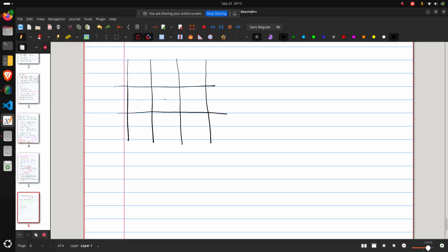Back to our Cartesian well organized meshes. This will make our life simple, but now you know how to go from a structured to an unstructured mesh based on how we compute the different gradients, and especially how we compute the secondary gradients, right.